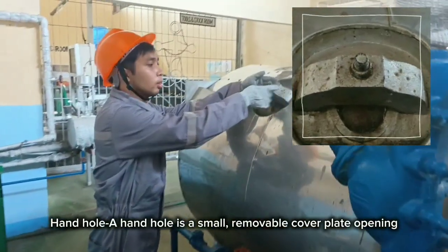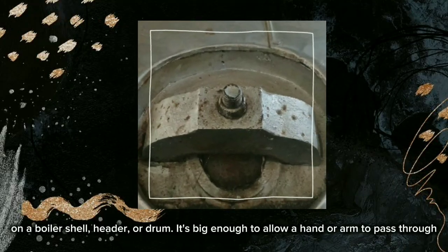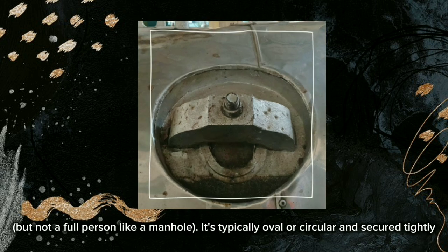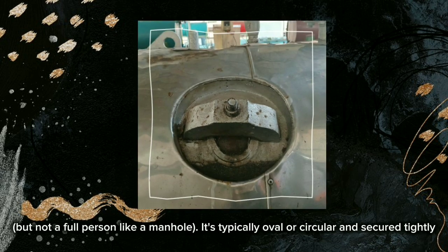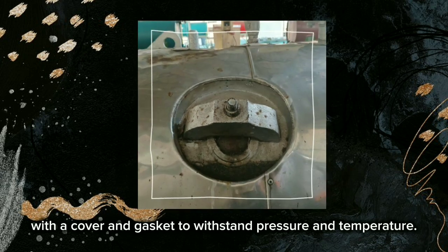Handhole. A handhole is a small removable cover plate opening on a boiler shell, header or drum. It's big enough to allow a hand or arm to pass through, but not a full person like a manhole. It's typically oval or circular and secured tightly with a cover and gasket to withstand pressure and temperature.